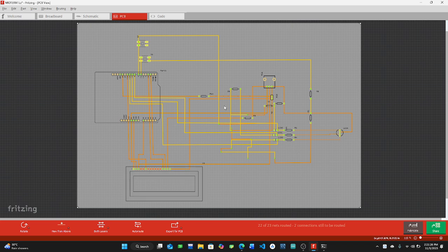As for the potentiometer, we have it to adjust the level of brightness of our LCD. We can see the letters through this potentiometer by adjusting it to the maximum and to the minimum.